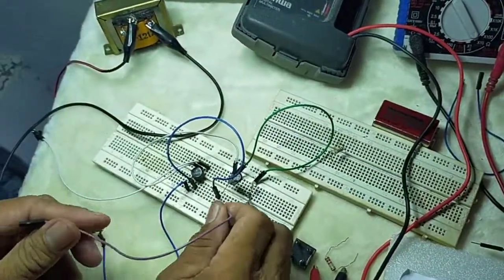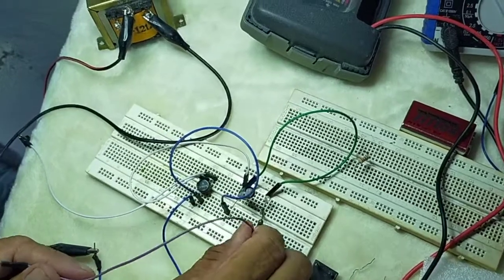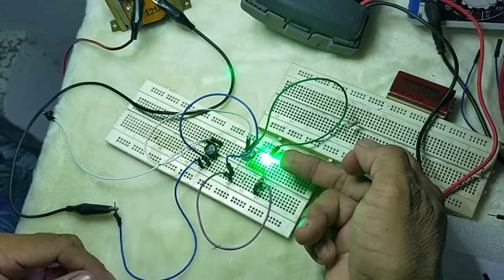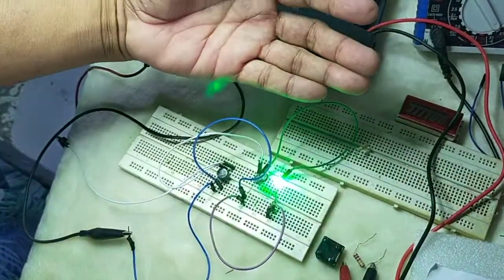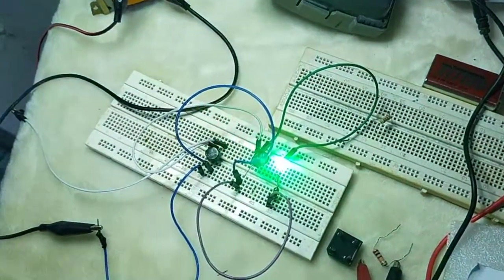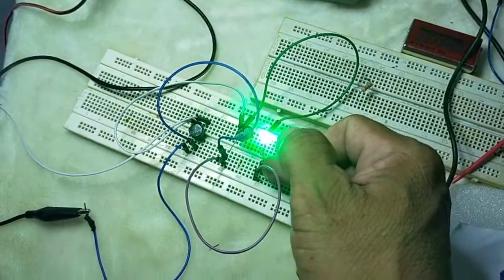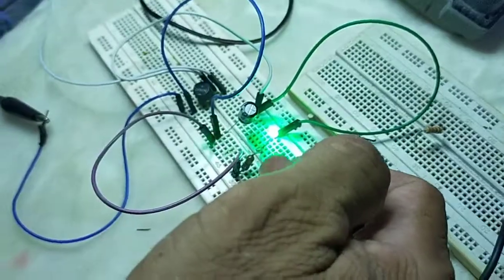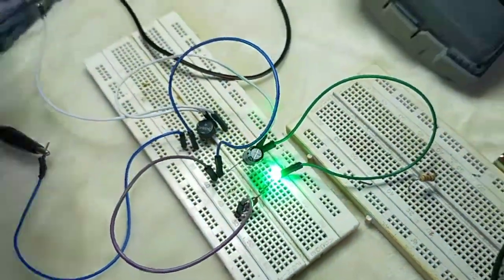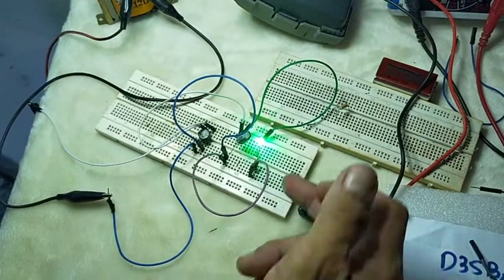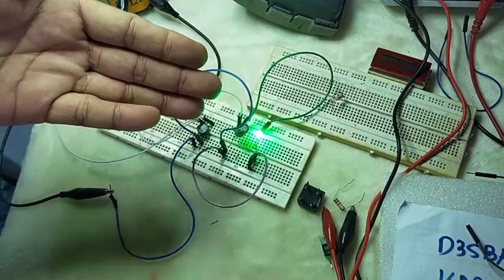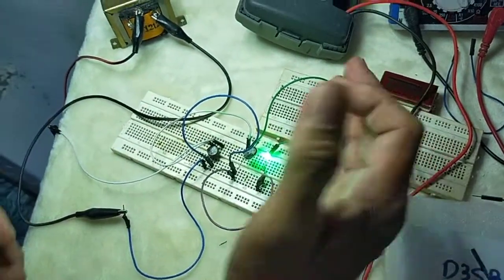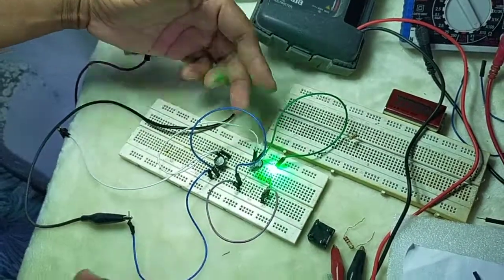I'm very sorry, class, for the inconvenience because of the technical problem here, losing contact of our breadboard connector. The light emitting diode, which is connected right at the output, serves as a power indicator. It is actually in series with this resistor. So, how do you choose the resistance of a resistor to be connected in series with the light emitting diode? Because without the resistor, the light emitting diode will blow or will be destroyed, because it cannot withstand the voltage output by this capacitor.